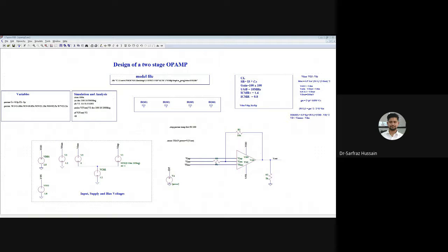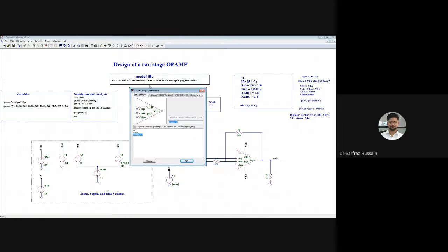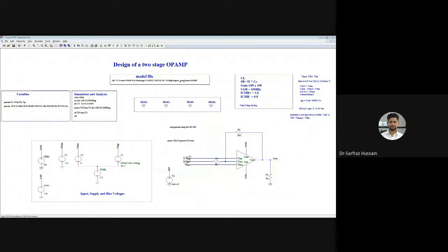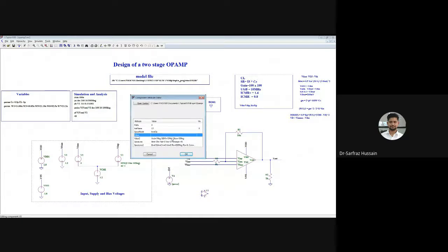And there are some more things, like op-amps also. If you go to this particular component part, okay, I'll show you this one. Here, if you go to this op-amp part, there are some op-amps which are universal op-amps. Okay, so you can also choose these universal op-amps, and let me just show you one. In this universal op-amp, as you open this one, you'll see these values are already given: the gain value, the phase margin, the slew rate, and the gain bandwidth.